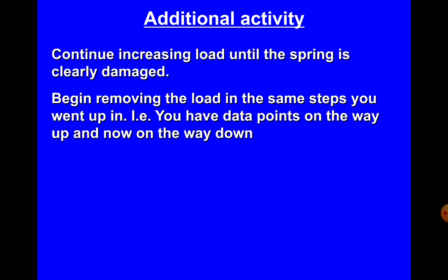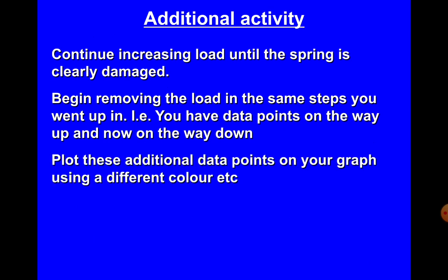Okay, and then we plot the load, which is in Newton, against the extension. Now we can also look at what is going to happen with the behavior of a spring when we even add more masses to the spring, and to see how the spring is damaged. And what will happen if we overload the spring and we are unloading the spring again. It's interesting to see, and you plot everything in the load extension graph.